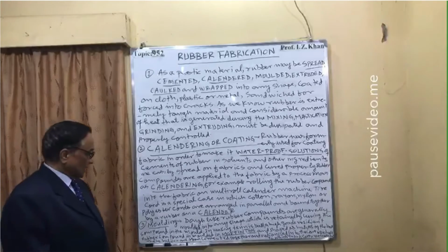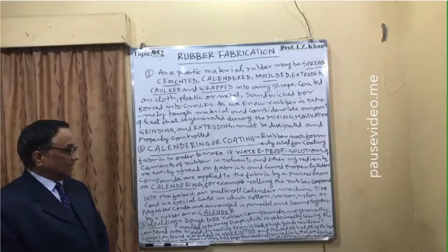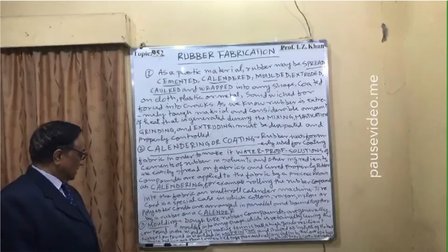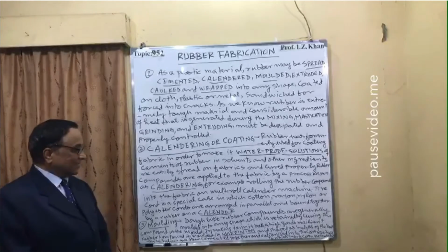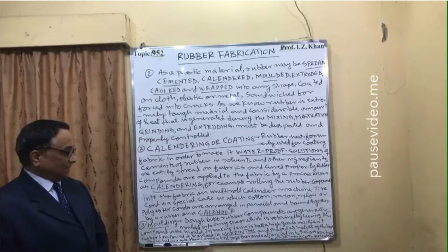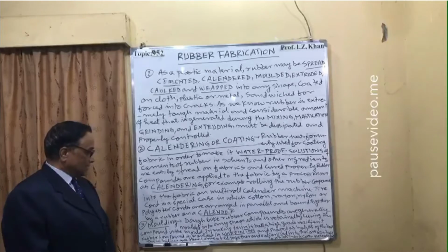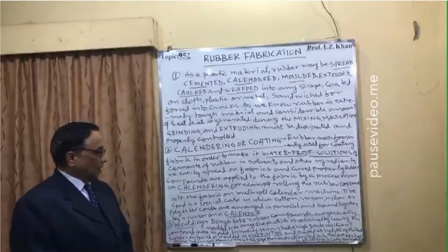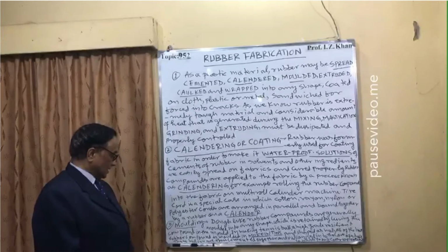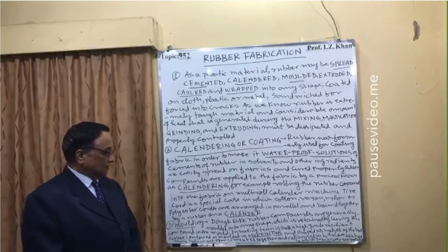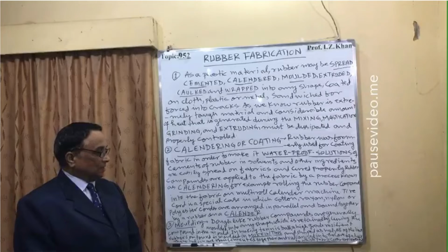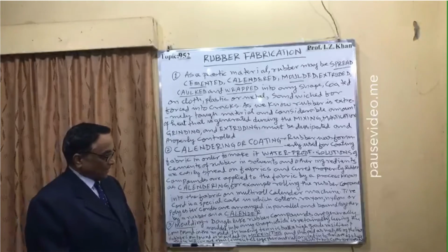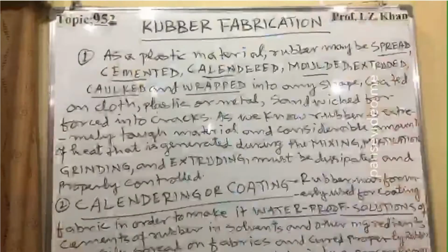Number three, molding. Dough-like rubber compounds are generally molded into any shape, which is retained by curing the compound in the mold. In making a tennis ball, a high-grade resilient rubber compound is molded in muffin tins and shaped as the halves of the ball. These halves are then cemented together and vulcanized into the core of the ball, to which the fabric cover is cemented.